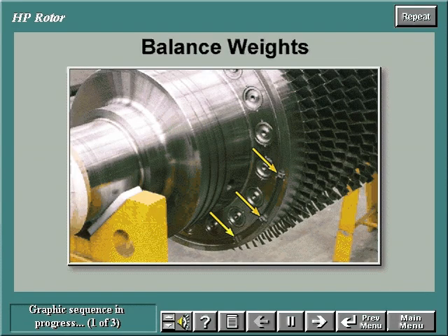Once the high-pressure rotor is completely assembled, it is slow-speed balanced. Balance weights are inserted and staked in place to make sure vibration levels meet design standards.